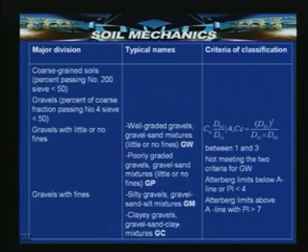Clayey gravels, gravel sand clay mixtures. The Atterberg limits of this particular soil, with the clay fraction, have a plasticity index greater than 7 and fall above A line. That indicates clayey gravels or gravel sand clay mixtures, indicated with GC. So, for gravels with fines, the group is GC if the Atterberg limits fall above A line, with plasticity index greater than 7.